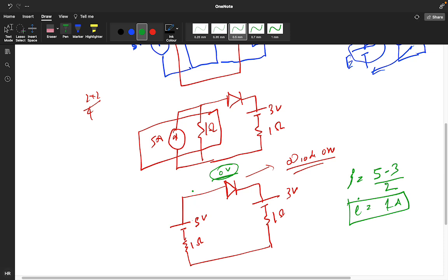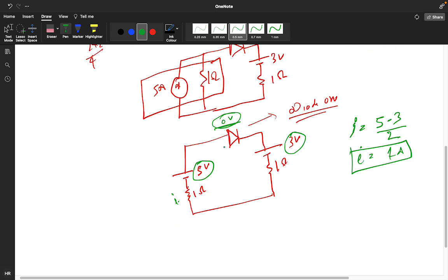Or you can see now, it means it will be on. Why will it be on? Because it has a positive 5 volt here and 3 volt here, and here some current will develop. Means suppose we have I. Okay. And if you are taking positive, negative, V forward. So if I am assuming V forward, it's conducting. So V forward will be 0 because it is ideal. But in a non-ideal case, the forward voltage, you have to assume 0.7. 0.7, in the non-ideal cases.